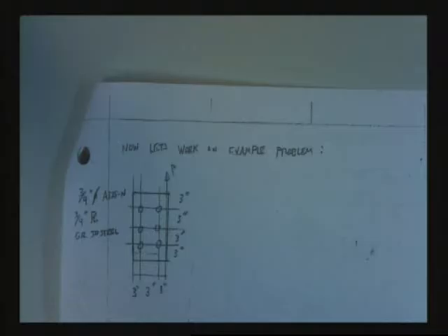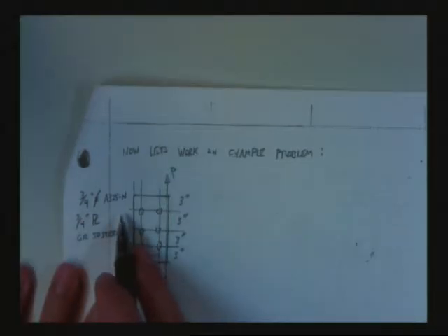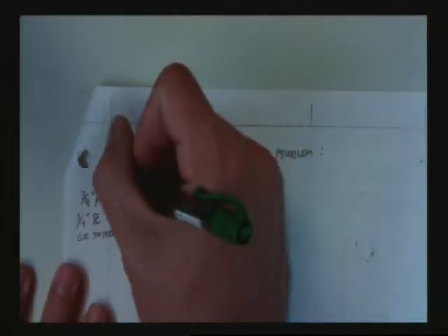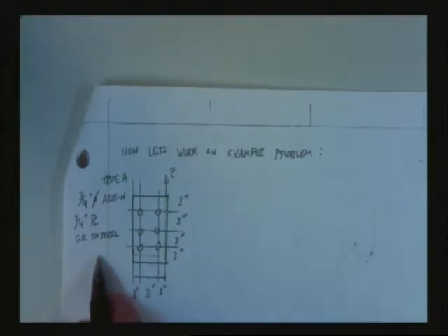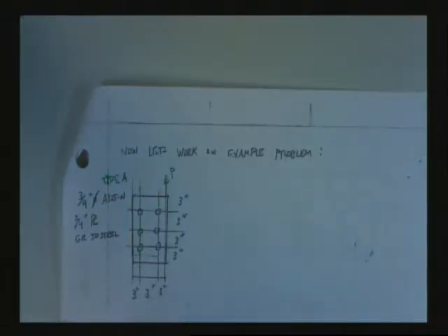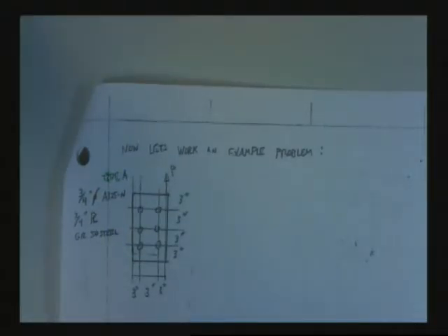Okay, so we're going to take 3/4 inch A325N bolts. I think those are also called Type A bolts in the new 14th edition. 3/4 inch plate, grade 50 steel. That's our bolt layout. Pretty symmetric.